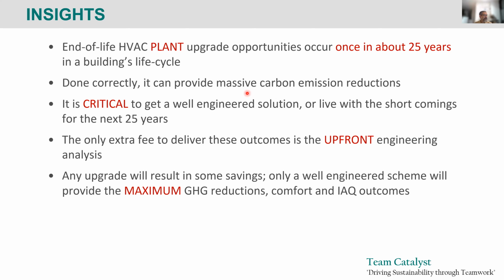Now, a lot of well-meaning engineers, particularly incumbent engineers who are looking after a building for its life, tend to do what is called like-for-like replacement. So you have a 1,000 kilowatt chiller, you're going to put in another 1,000 kilowatt chiller. Actually, that is absolutely the wrong step.